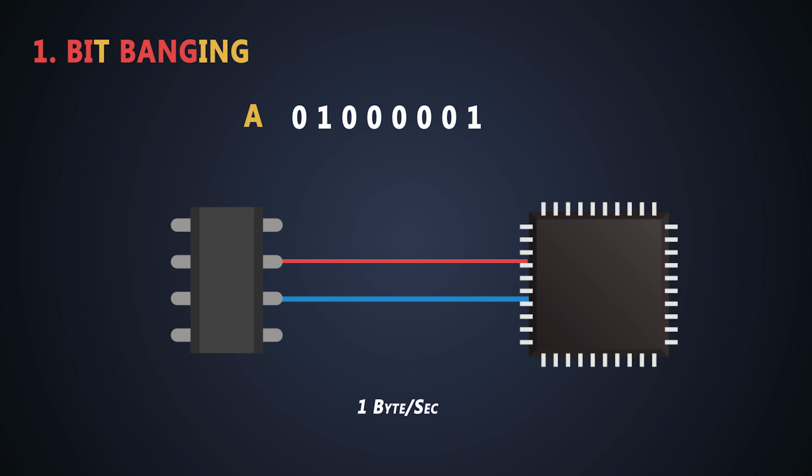Initially pin 2 is high. When it wants to talk, it will go logic low, that is 0, for a single clock pulse, which is 1 second, to notify the other device that the controller is about to send the data. Now the controller will start to send the actual data, and initially it will send the LSB of the data, which is 1. So pin 2 goes logic high. Then it will stay high for 1 clock pulse, which will be given as a delay in the microcontroller.